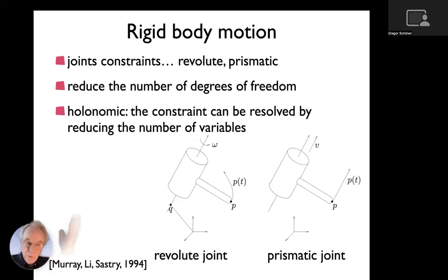So that's just mathematically what you do with a rigid body, and then you build a robot from rigid bodies. The different segments are rigid bodies that are connected to each other, and the way they are connected to each other imposes constraints, joint constraints. So the typical industrial robots only have really these 2 types of constraints: revolute joints, which really rotate around one axis, and prismatic joints, when you sort of extend an arm, right? We humans don't have prismatic joints. You can't just grow your elbow.